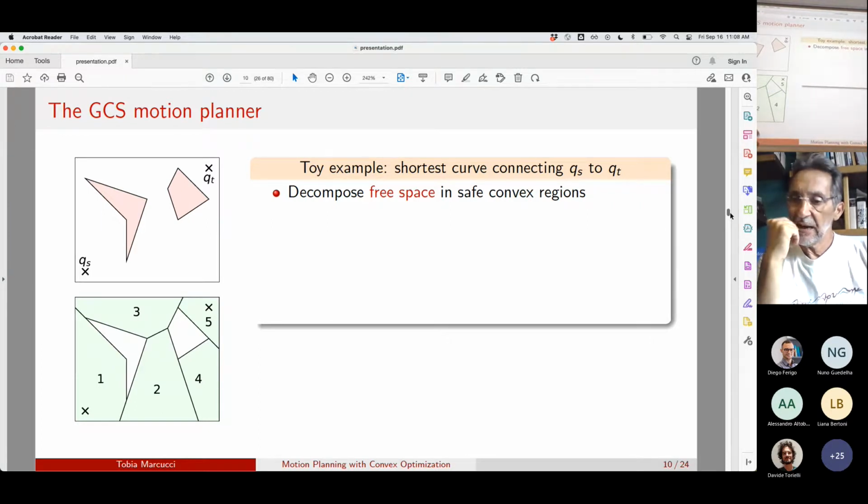You have seen that at the end we had these motions that were not really optimal. This was because maybe an obstacle was like this in configuration space in 14 dimensions, and we ended up with a region that was very conservative. It might be that we can have more regions to have better trajectories, but then you pay in terms of computation times. Okay, this is clear.